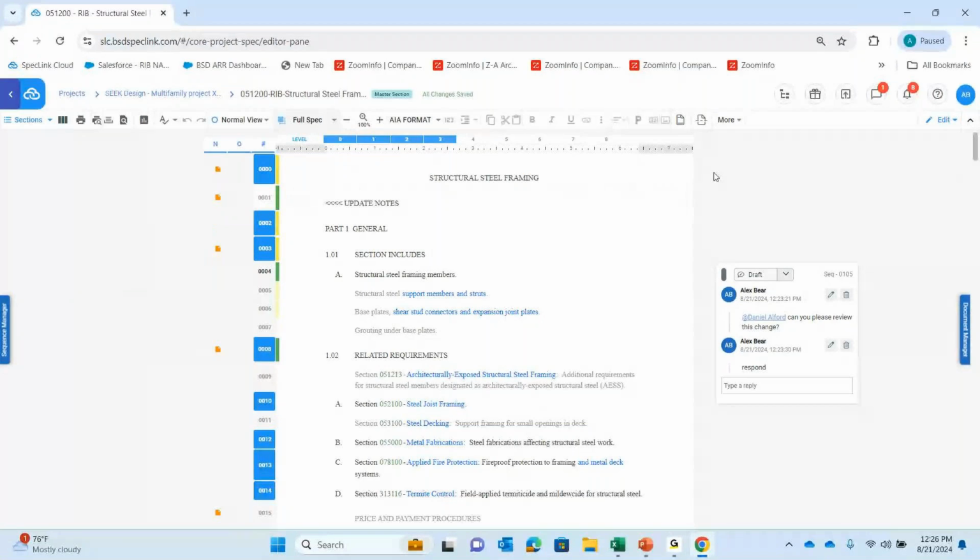We recently had a project where they installed some bricks high up with no brick ties, and the bricks were falling off the top of the building, and we were like, "What?" And in the specs, it had the whole assembly. It had all of the requirements for putting the masonry on the building. So there's an instance where the specs save the day, because what happened is, you're going to go up there and fix this for free because you didn't install it per the specifications.